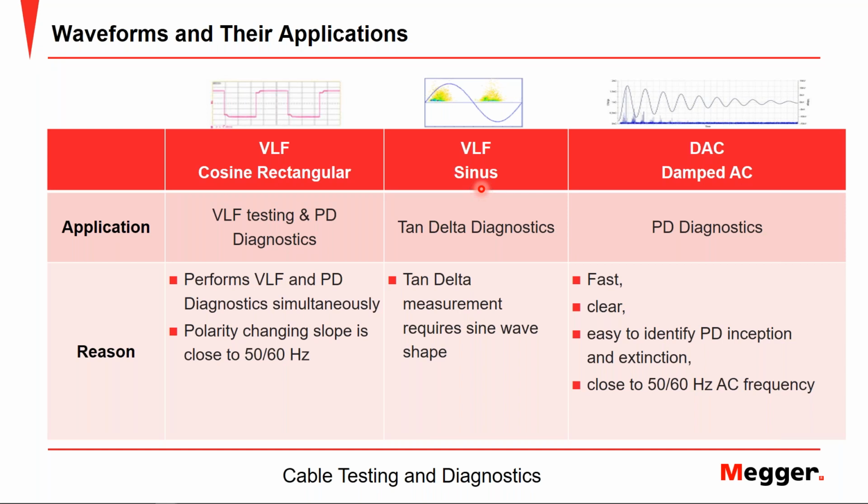Now you have VLF sine, which is a very common waveform. And really the recommendation is to use this for the tan delta diagnostics, because it's required to use the sine wave for tan delta diagnostics.